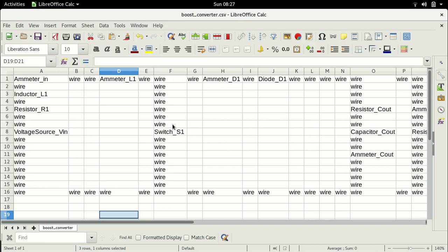Right? So this is something which we'll talk about in the next lecture, where we will get started with transformer simulations. But the idea behind this lecture was to lay the foundation for why we need isolating transformers in boost converters. That is, theoretically, we can increase the duty ratio to anything we want, but practically, there is a limit to the duty ratio beyond which your system is at risk. So you do not want to increase your duty ratio to any limit you want, right? With this, I'm going to stop this lecture. And as I said, in the next lecture, we will start simulating a transformer.